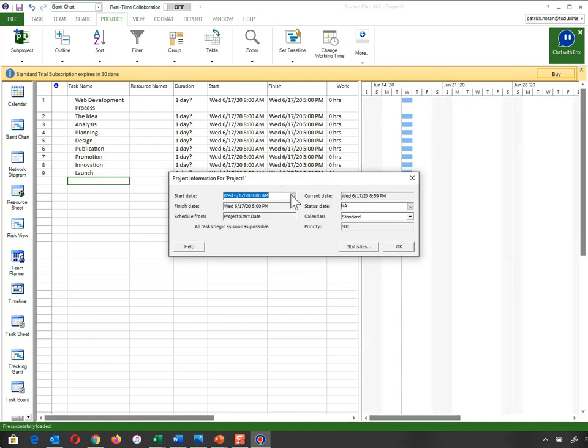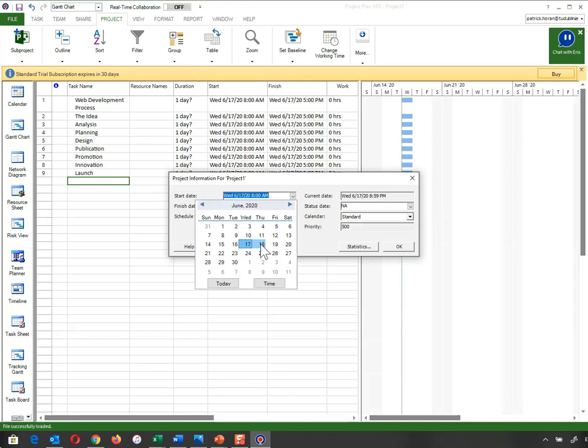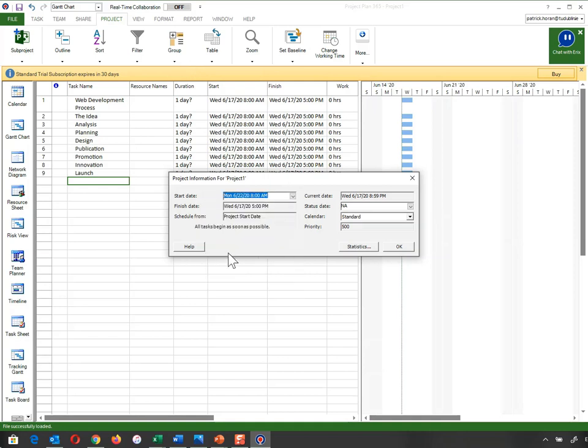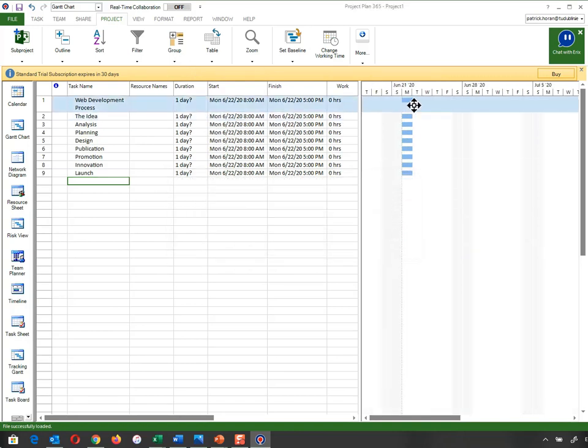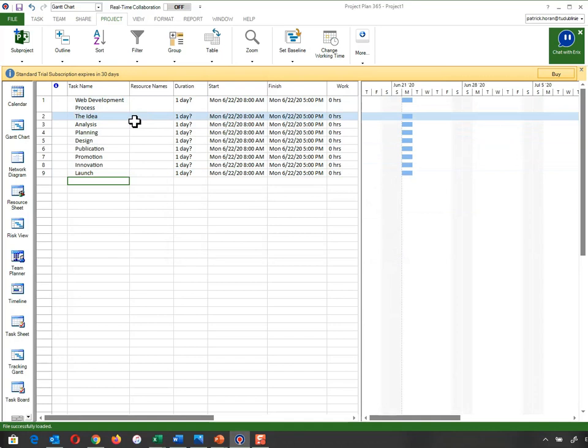So I'm going to say that I'm going to start my project on the 22nd of June, okay? So that's my start date. I'm going to go OK. Now you should see that this will change over to the 22nd of June when I go OK. Okay, and it goes to the 22nd. Now you'll also notice that I can set my start date for something in the past or well into the future. Okay, once I've set my start date, the next thing I'm going to do is I'm going to change my working times. At the moment, my working times are, if you just look over here, you can see Saturday and Sundays are hazed out.